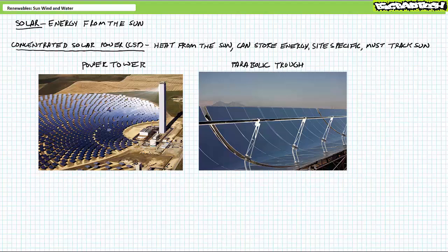A parabolic trough, in contrast, uses a long reflecting trough that focuses sunlight onto a fluid-filled pipe located along the focal line. In both these scenarios, the sun-heated fluid in the reservoir or pipe is sent to a heat exchanger to generate steam and then used to generate electricity, as would a regular turbine driven by a thermal cycle. Or this heat can also be stored for later use.